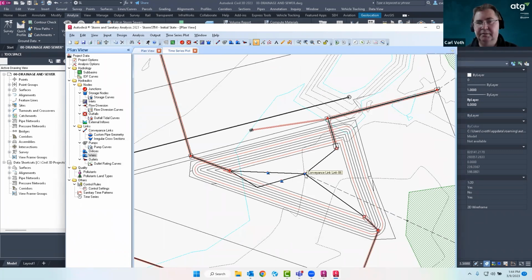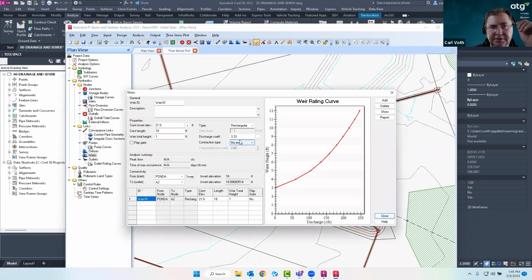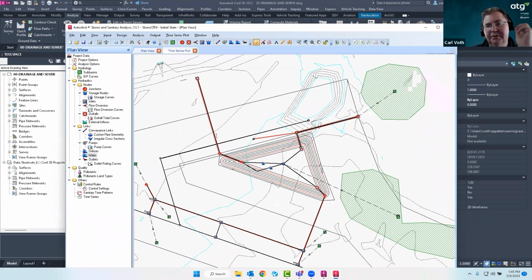And so now our pond first controls by the output, the orifice out, and then it gets controlled by the weir. And the reason why is because of the elevation that this one's going to be set at. So in this case, this actually needs to be at 18. No, was it 19? 19. Let's go back and set this one to, that's at 21, so that one's fine. All right, so now all of those are being modeled all at once within our system here.